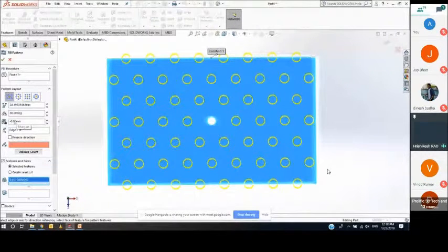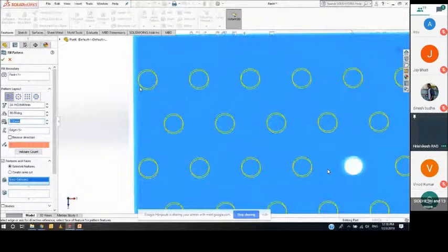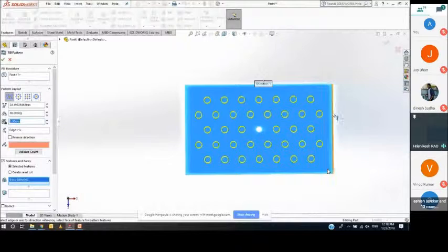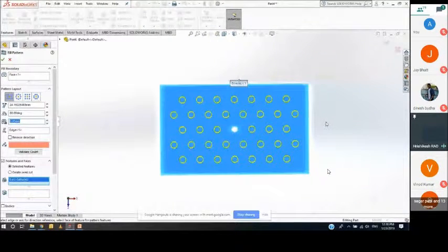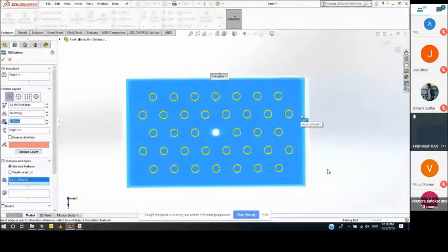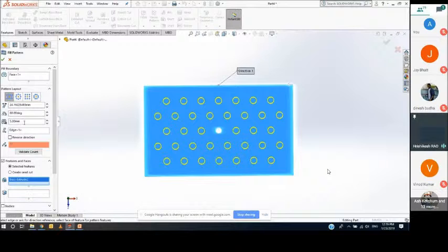Here you'll see if I set minus 8 mm, it is going above that. I'll just say 2 mm. So automatically, there's a gap of 5 mm. This might be more than 5 mm because if we create one more instance of that pattern, the margin for 5 mm will not be applied. That is the reason why it has just kept one more instance so as to maintain the 5 mm margin.